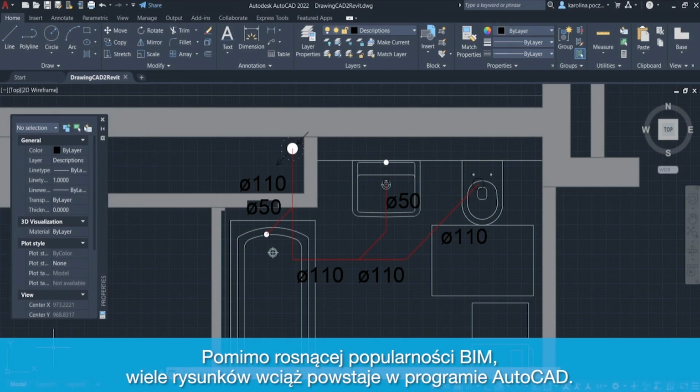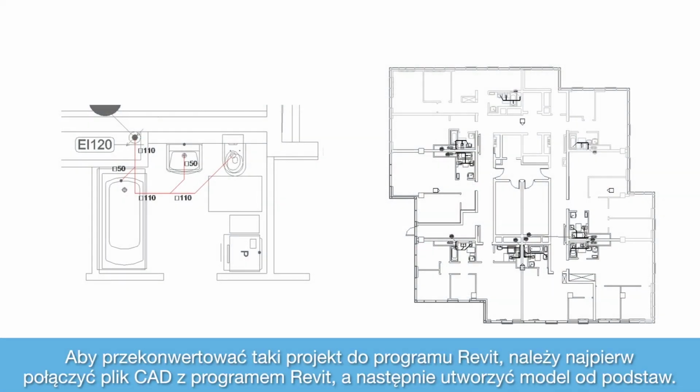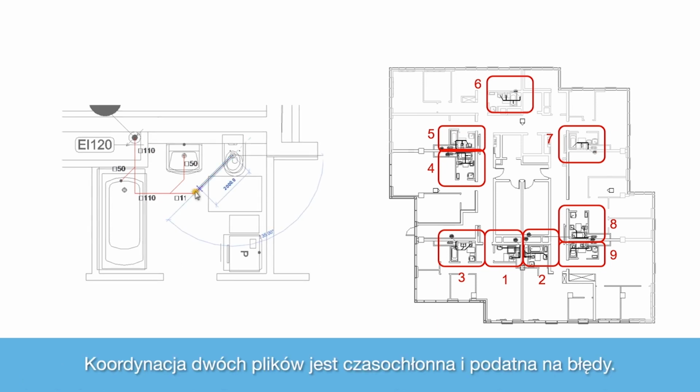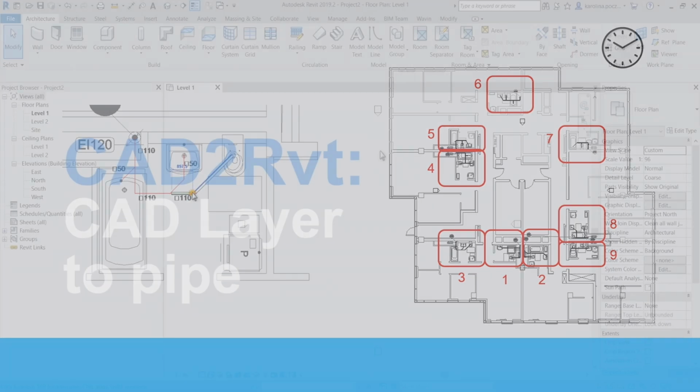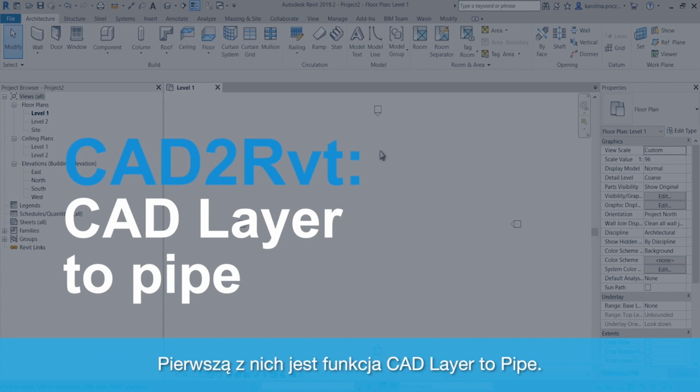Despite the growing popularity of BIM, many drawings are still being created in CAD. To convert such project into a Revit file, it is necessary to first link the CAD file to Revit and then create the model from scratch. Coordinating the two files is time-consuming and prone to errors. To facilitate these exact issues, Wavin introduced two new features, the first one being CAD Layer to Pipe feature.